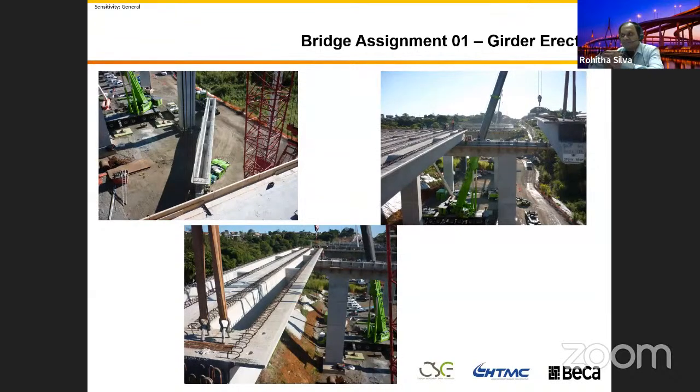Can someone answer me? There's an obvious reason I can't use it. If you know the numbers, you can tell me easily. Because... that's right, Malik. The creek width is 30 meter. Your span is 28 meters. Then whatever span arrangement you go, there will be a pier within the creek.